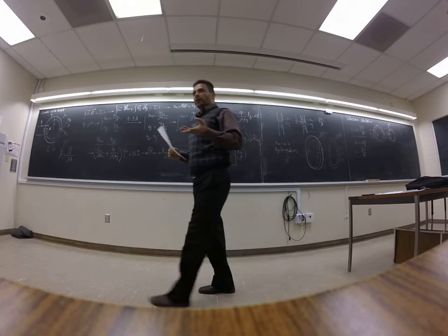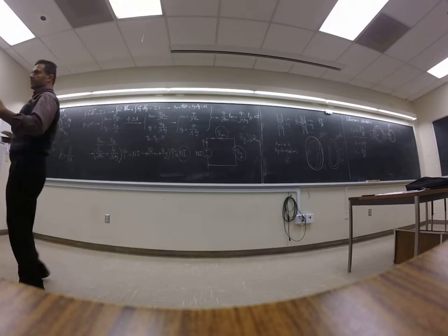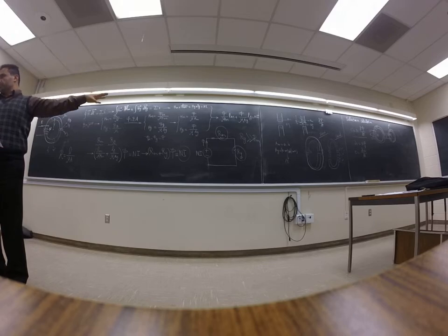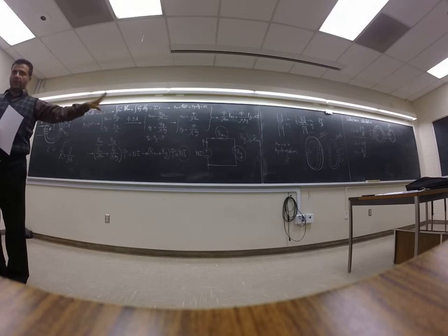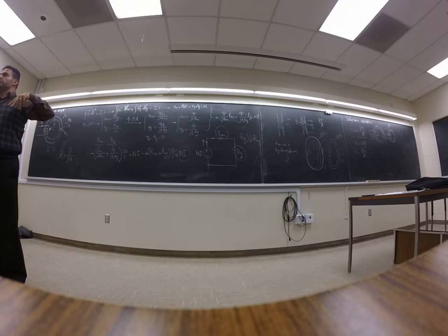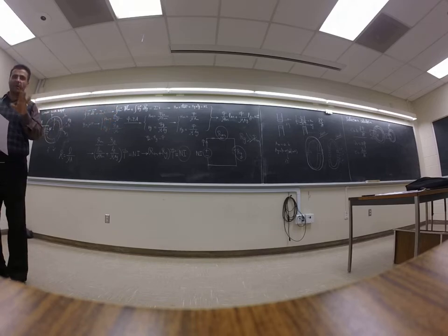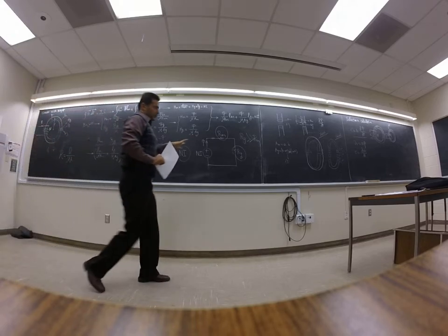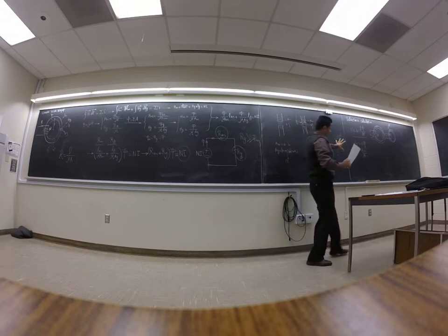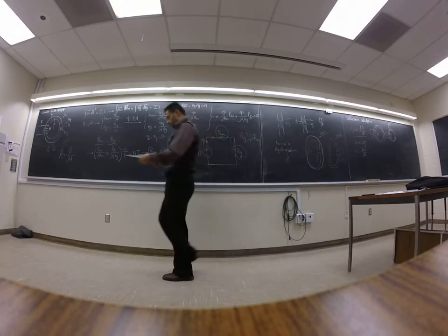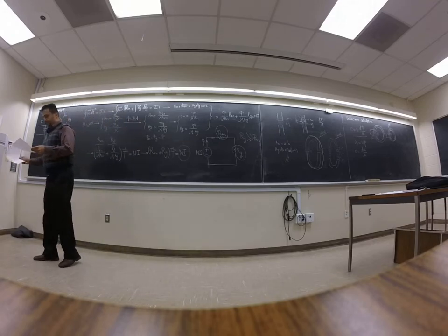They call it Lenz's law. What the Lenz's law said, he said the induced current or voltage, they oppose to what caused them, right? It means it's going to generate another current to go cancel what caused this voltage. This is exactly how transformer works, you know. So, but this is the induced voltage in a winding when it has an N turn. So the induced voltage in the winding is the dphi over dt.